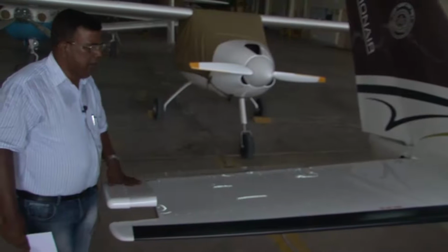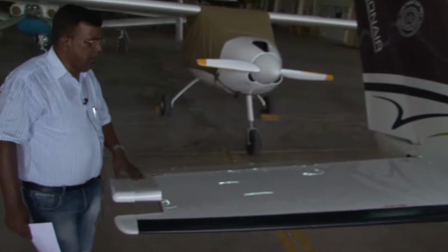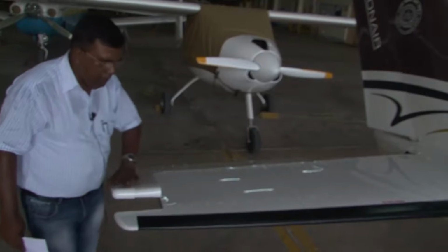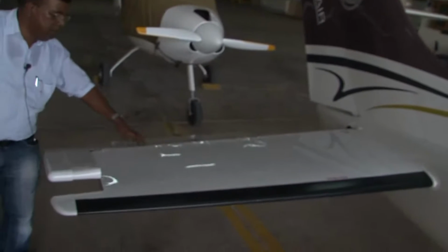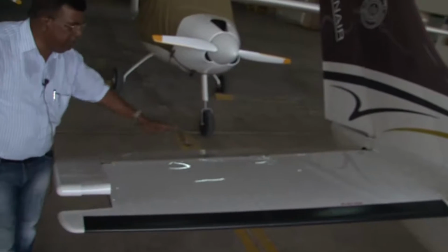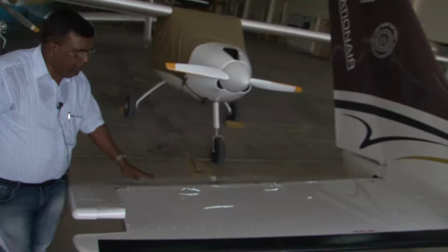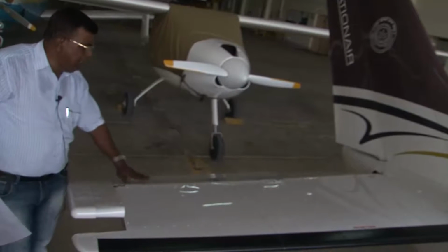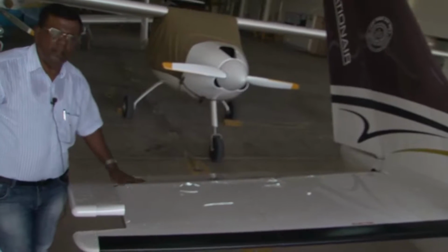Okay. See, this is a very important part of the airplane. This is called stabilizer, you all know. So as a designer, if you want to conceptualize this configuration, if this whole is the horizontal stabilizer and this much portion is the elevator, then I should try to know what percentage of area is being used as elevator. And from this you could see that this is around 30 to 35% of the whole stabilizer area.